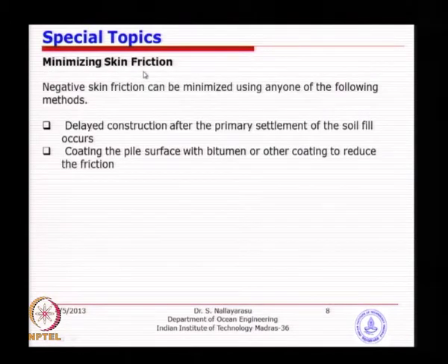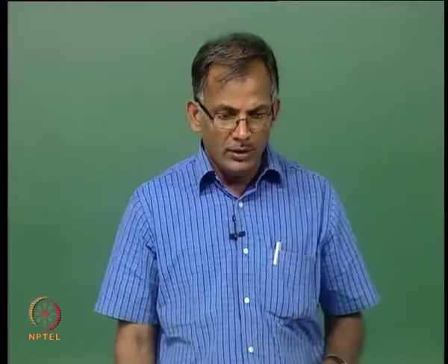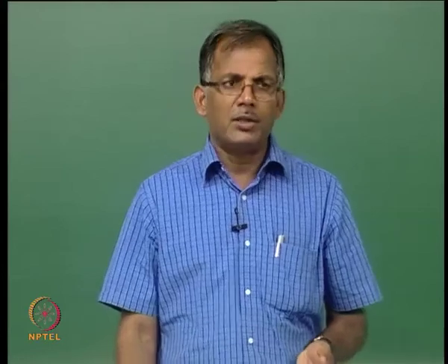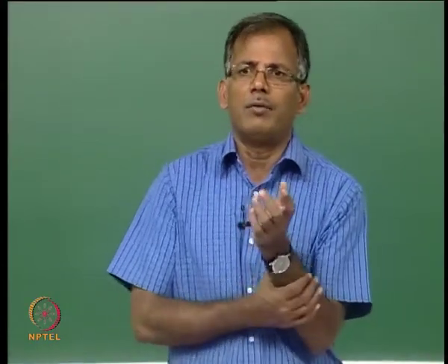So, how do we minimize skin friction if you have to install piles in an area where some top layer fill is expected? You could delay the construction, that means you allow the consolidation or immediate settlements to happen. So, wait for 6 months, 1 year, 2 years, or you actually accelerate the settlement by means of overloading. In several places in onshore construction people do this by stacking heavy weights. So, if you are having a fill, that is fine, but you make 90% or more of the consolidation settlement happen before you construct the structures. By doing this you minimize the amount of settlement that is going to happen post construction, but it all depends on time. And basically there are several methods of soil improvement techniques, which I think we are not talking about in our course, but it will be very important.